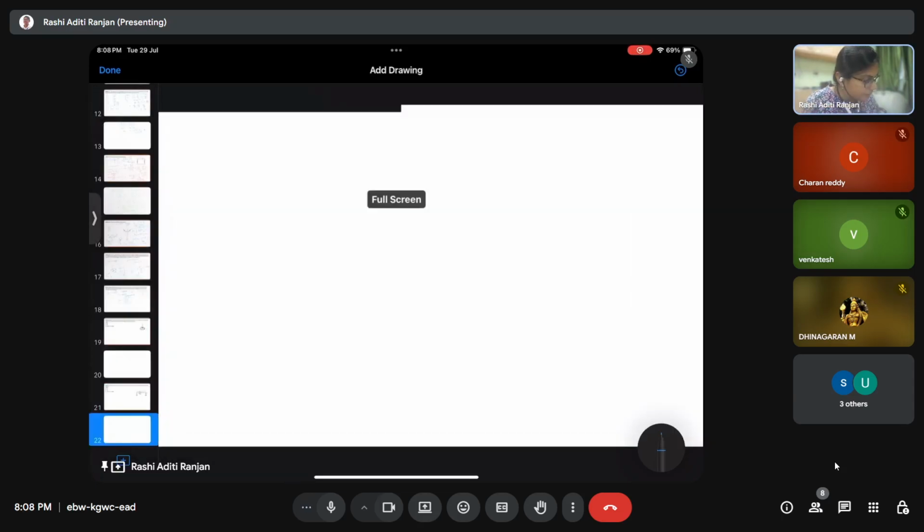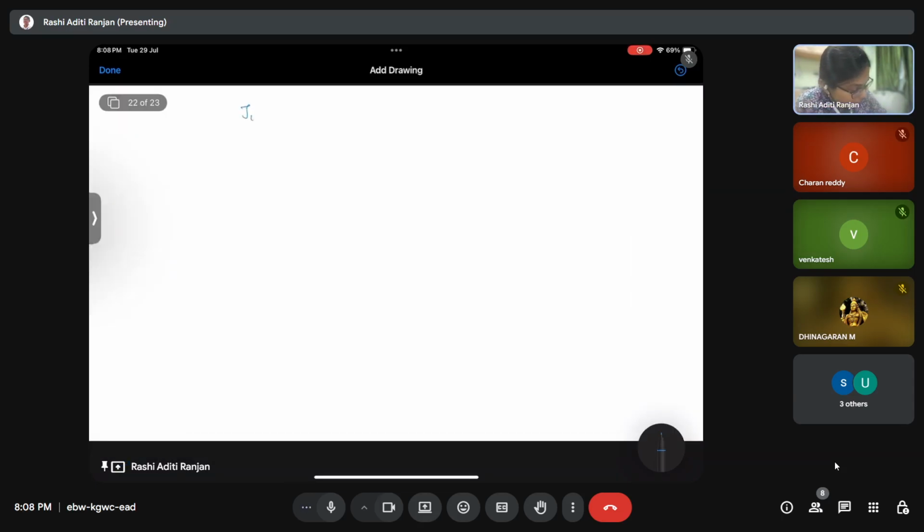Now we get J naught theta double dot is equal to minus K A square theta minus K B square theta. This will be J naught theta double dot plus K times A square plus B square theta is equal to 0.